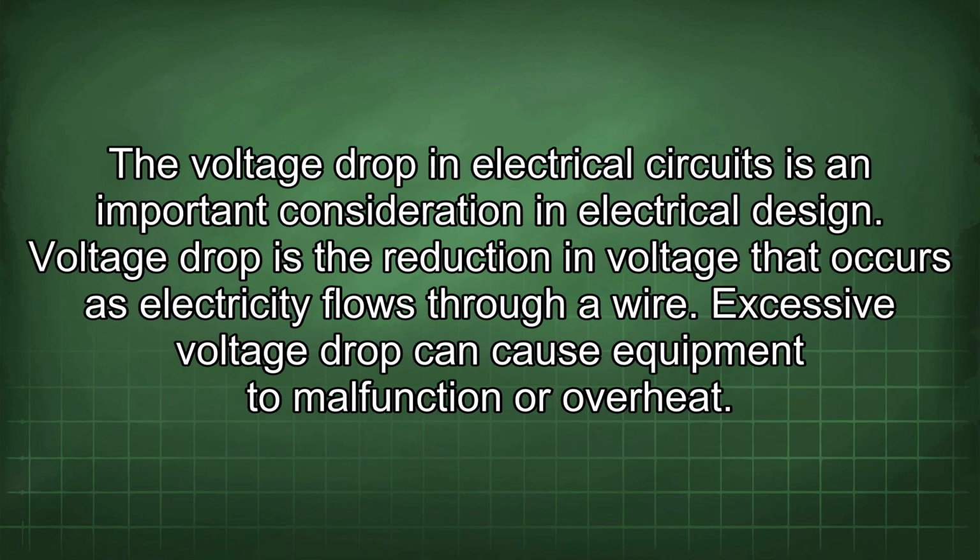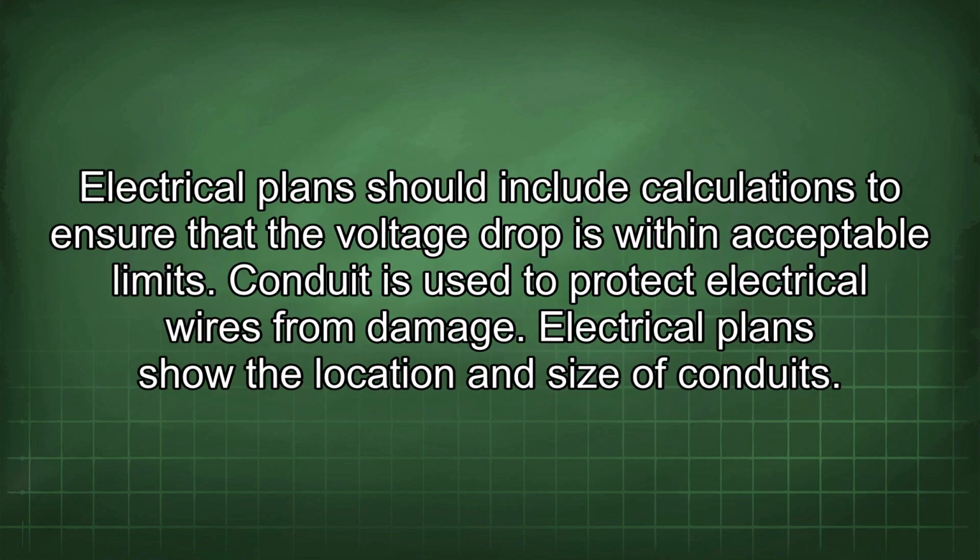The voltage drop in electrical circuits is an important consideration in electrical design. Voltage drop is the reduction in voltage that occurs as electricity flows through a wire. Excessive voltage drop can cause equipment to malfunction or overheat. Electrical plans should include calculations to ensure that the voltage drop is within acceptable limits.